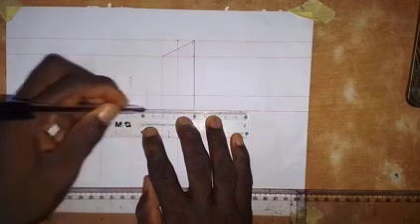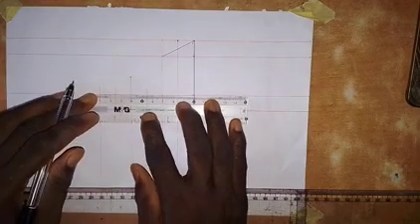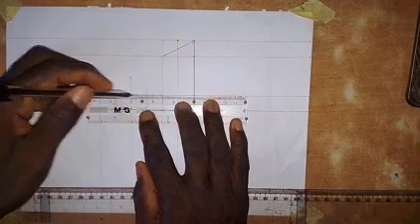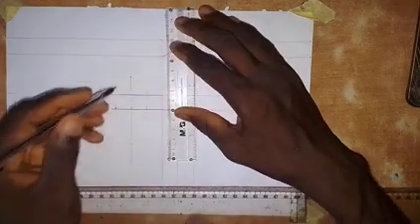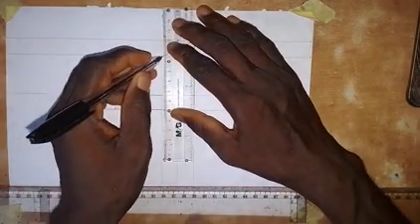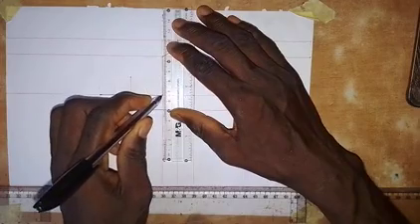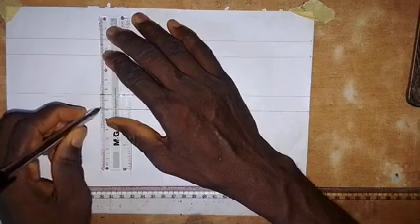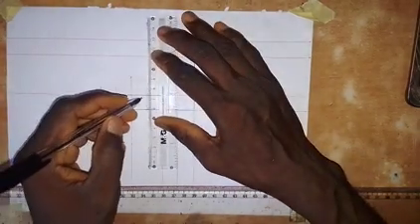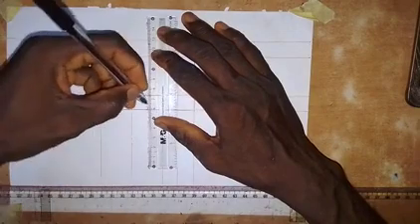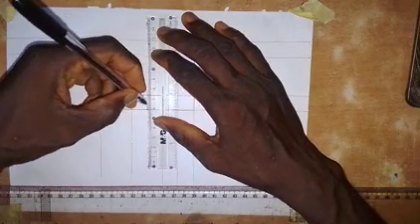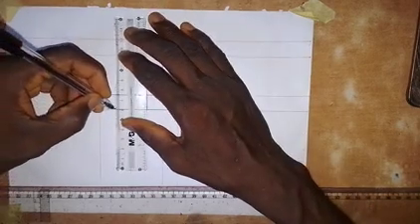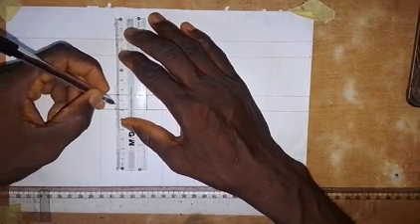Then this line from here to here is a thick line to this point, and we make this line a thick line from here down to this point, and this line also. For the hidden parts, it will be easy in the front elevation, so we draw short dashes line on this line, and also we draw this as short dashes line.